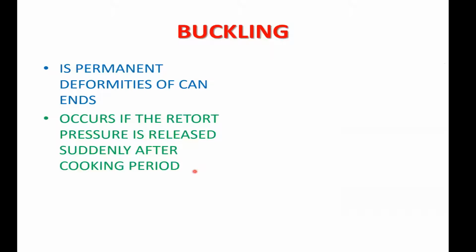After sterilization, we will be condensing the steam around the cans. You remember that or not? When you inject the water, the surrounding steam will condense faster, so the inner pressure will be higher than the outer pressure. The pressure inside the can will be higher than outside. Is it clear? If you are not counteracting that pressure, the cans can break, or the seams can break. That is called buckling.